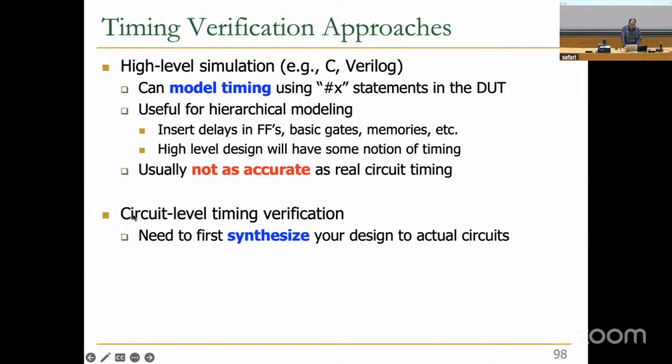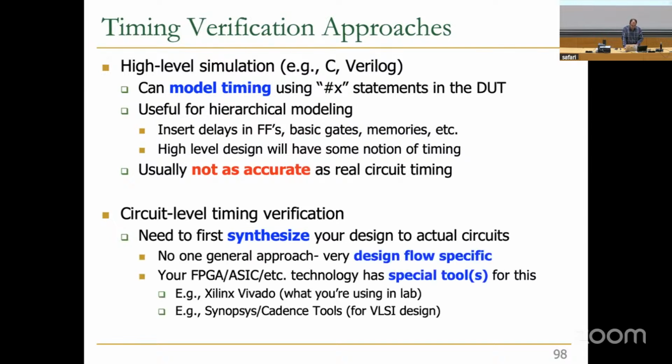But there is also a way that you can use a circuit level system simulator like HSPICE, for example, that you can synthesize and then try to simulate SPICE model of your circuit that has the model in transistors, and this SPICE model can basically model all these resistance, capacitors, transistors that you have, and then you can probably get much better understanding of your latencies.